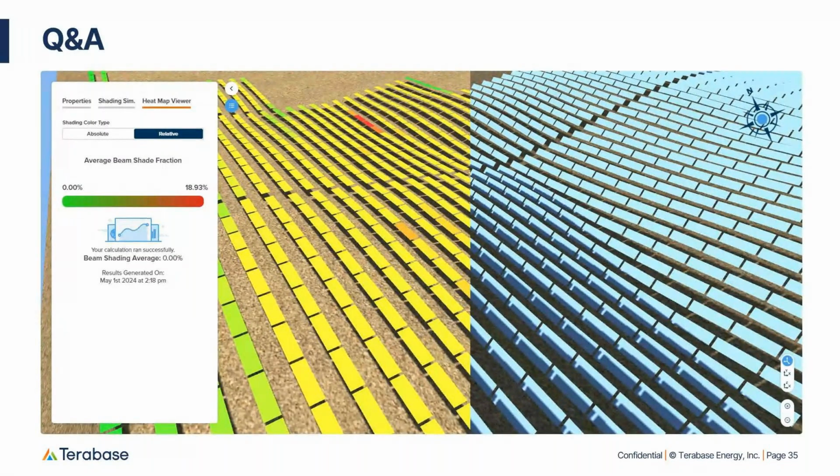Are there plans to add other trackers into the irradiance optimization dropdown in addition to Array SmartTrack? Yes, we're hoping that this is the first integration of many. Array Technologies' trackers are generally gang trackers, so they follow similar tracker angles. Being able to do this on an individual tracker basis is a little bit more complex, but the plan is to extend that further.